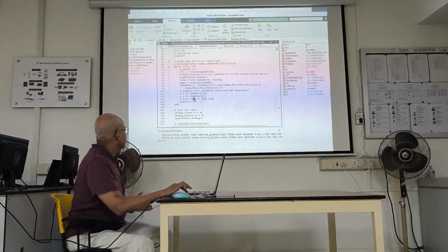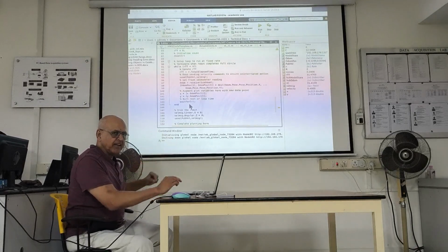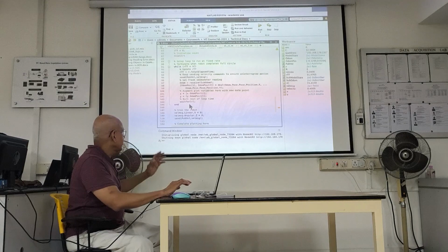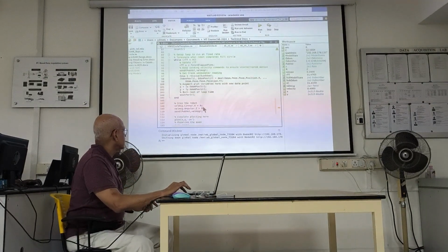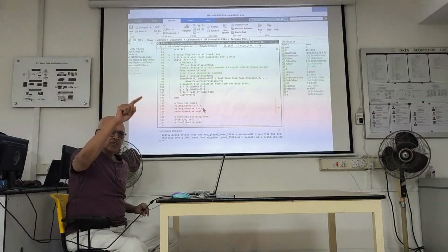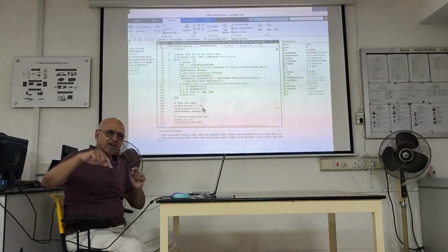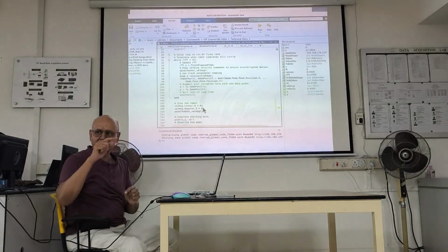And that's it. It'll come out of the loop, hopefully. This is a program that ends. Typically robots go on forever, right? And you hit a Control-C when the mission is done. Here it'll come out. And then you can stop the robot with this command. So when you trace out that L in the homework, you need to stop the robot, or else the plot will go like that. So you need to stop it when the L is done, the L shape.